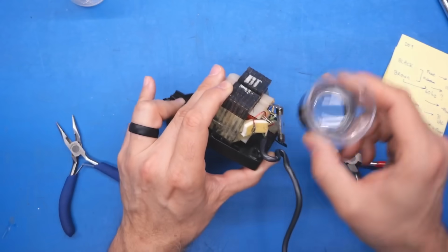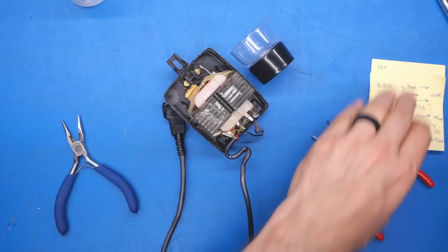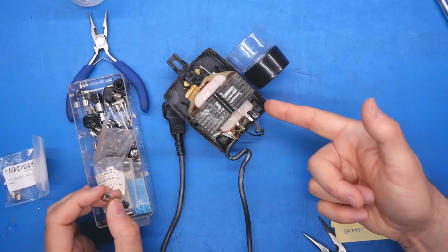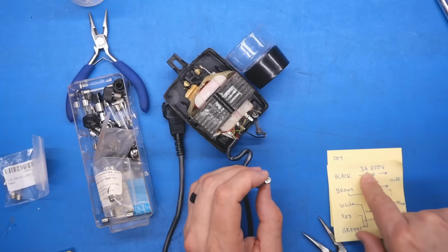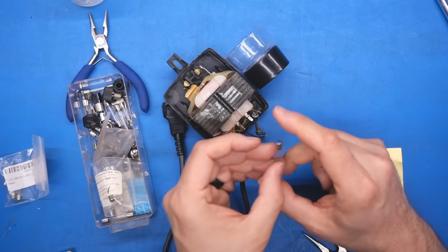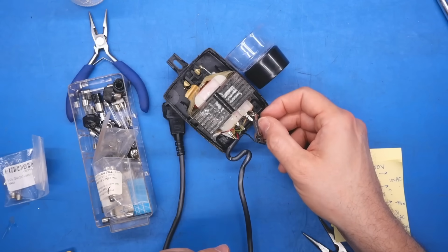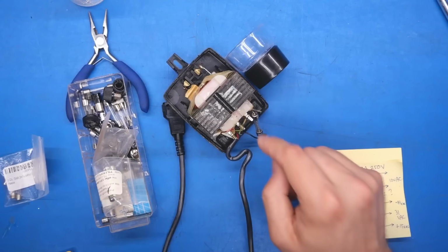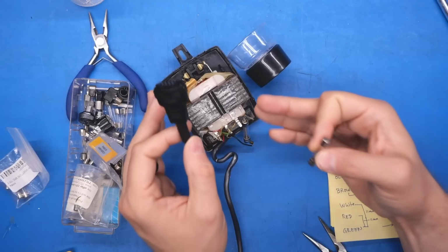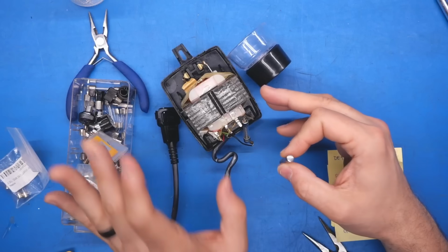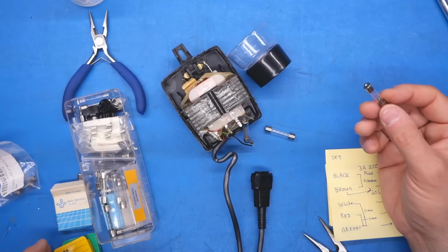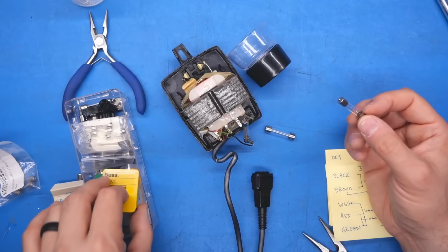All right, I was able to see that it's a 3 amp, 250 volt fuse. And there was no F or S on the current side, so it just said 3A, because sometimes it's a fast blow or slow blow. I'm going to judge by the fact that it's kind of thick inside that it's a slow blow fuse. And I know by looking at the bench power supply that about 800 milliamps is what this thing draws when it's normally operating. And I just found a 3 amp fuse. That should be a good fit.